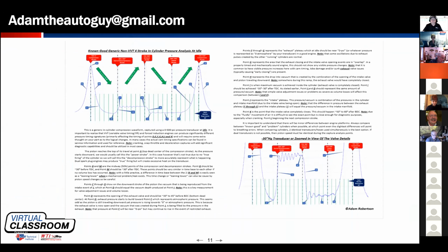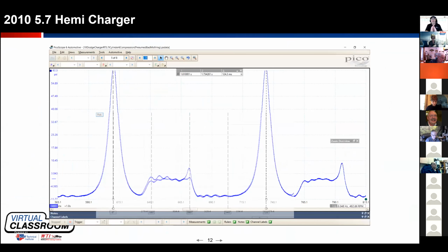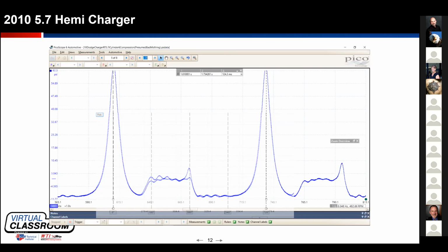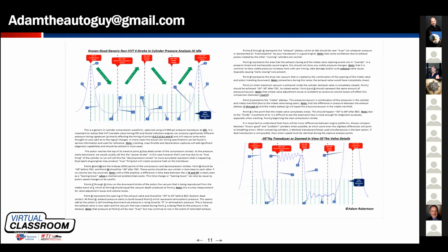But from this point forward, I just want to make this far simpler for us, far simpler. When you are beginning to take waveforms, like in this case, your in-cylinder compression waveform, if all you figure out to do, and I will show you this dynamically before the end of this class, if all you learn to do is take one cylinder from the car and overlay it over a different cylinder in the car, we're talking about not even truly understanding every one of these measuring points.